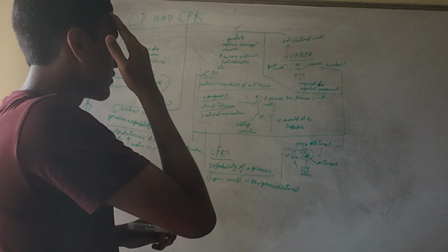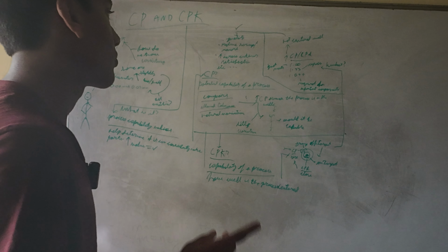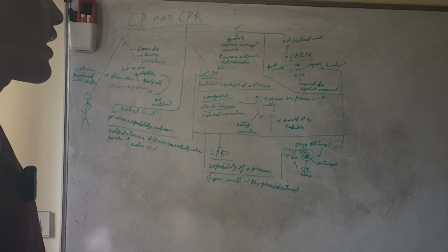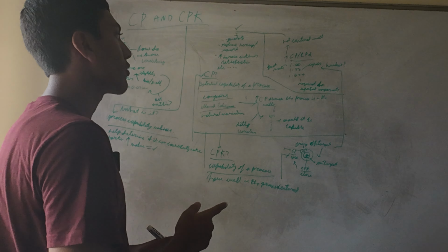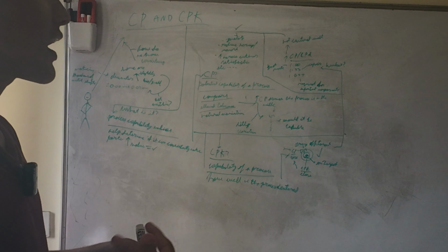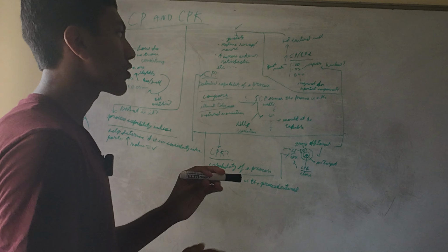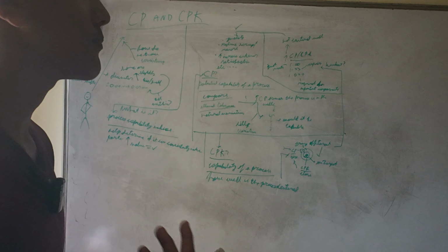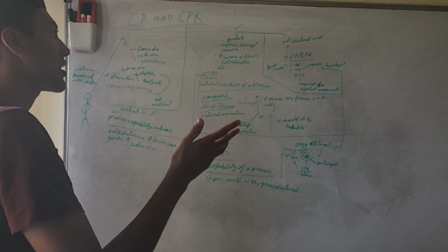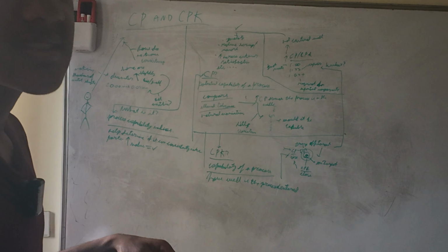Now, if the CP or CPK number is 1.33, then it's considered capable. And if it is 1.67 or higher, this is required for important components, meaning it can manufacture very well and is only used for super important components that have to be manufactured consistently. So those are all the numbers. And if the number is below 1, that means it's not centered well.